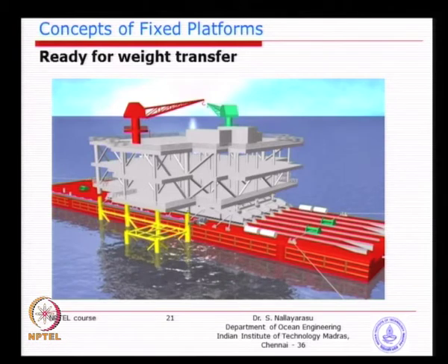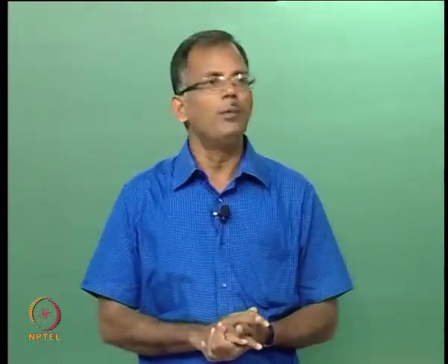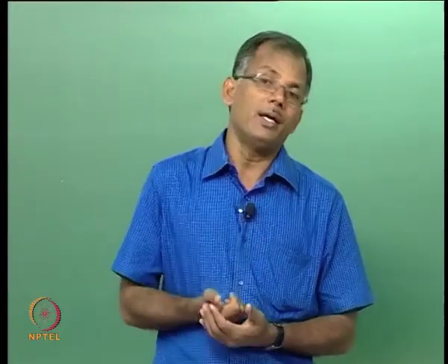Basically, whenever the situation is not right, for example, you start ballasting, and the rate of ballast and the rate of increase of water level due to your tidal changes matter. If the tidal changes are faster than your ballast, what will happen? You won't be able to touch down at all. So, is it a good idea to do this operation in a rising tide or a lowering tide? You have to plan it, but lowering tide is also a big danger, because if it goes faster than